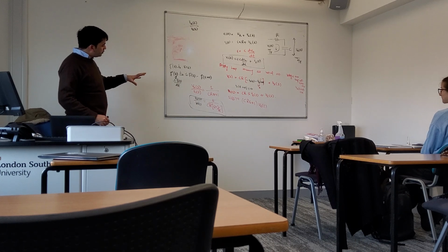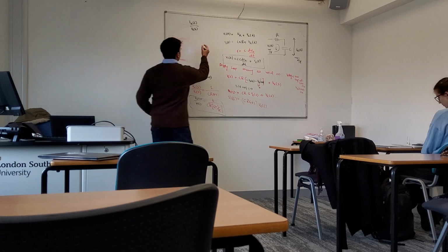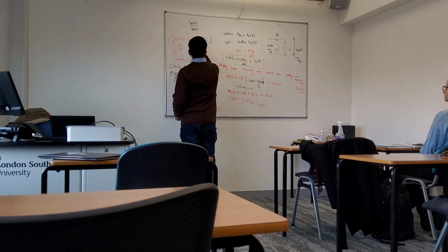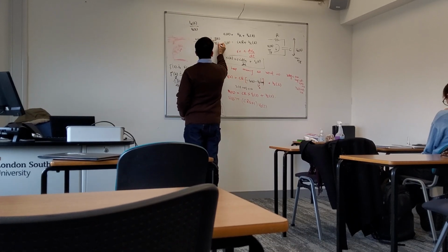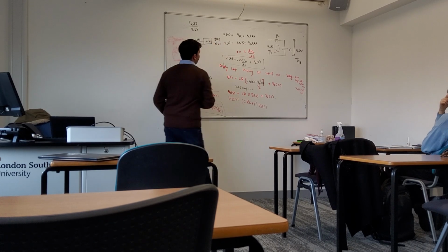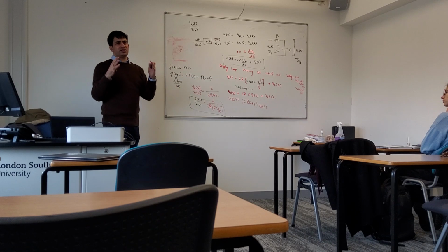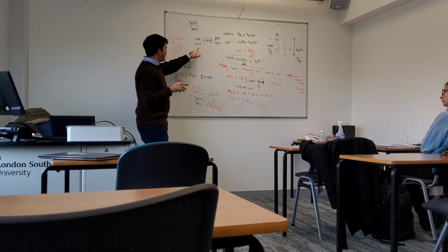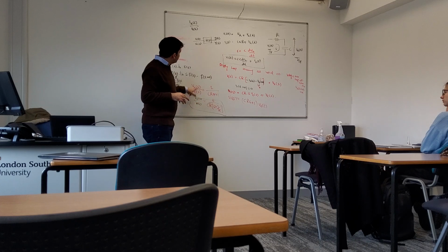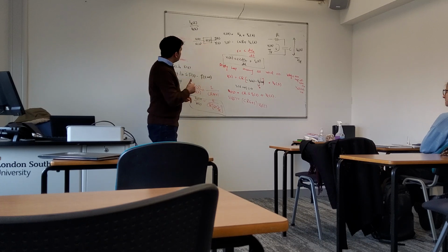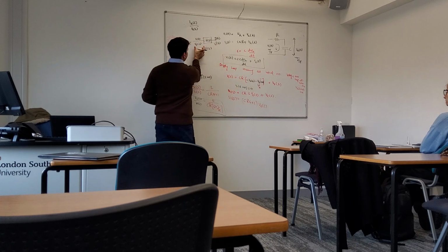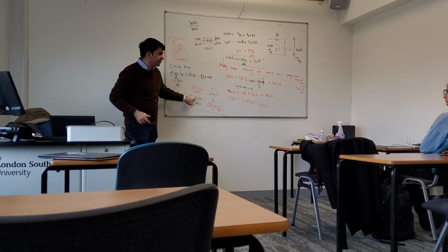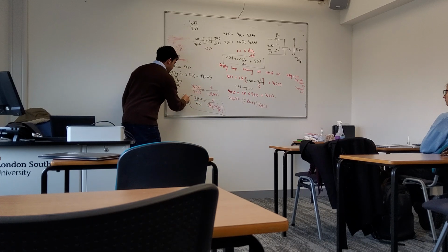Now, we have this transfer function. If I draw this box, it has x(t), y(t), X(s), Y(s). I don't know at the moment what the system is in the time domain, but I can say that this is H(s). In this case, H(s) relates V1(s) and V2(s). What does it mean? It means V2 equals V1 times H(s). So I can write this as a transfer function, right?